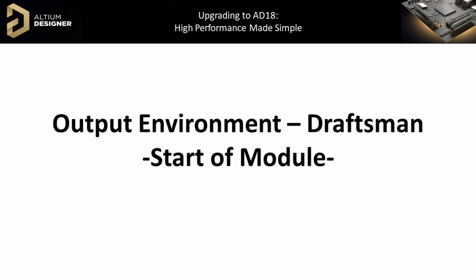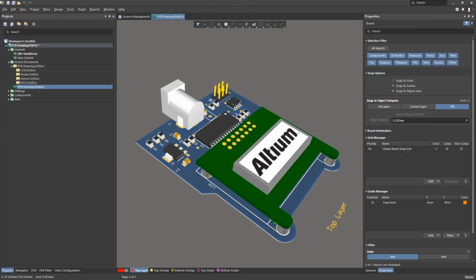After completing the design capture and layout, and configuring the bill of material for procurement, we can now produce the necessary files required for fabrication and assembly. Besides outputs like Gerber, NC Drill, and pick and place files, designers would also produce fabrication and assembly drawings for board design production. In this section, we will see the improvements of Draftsman document in Altium Designer 18 to facilitate creation of these graphical drawings.